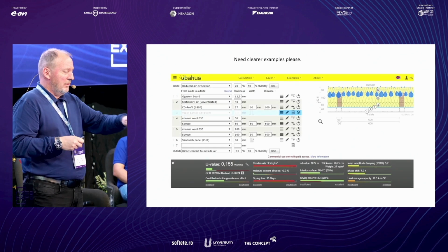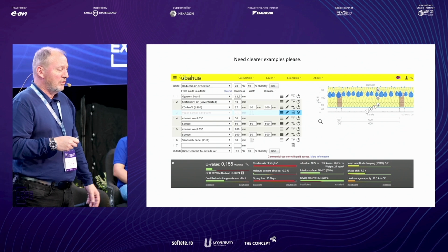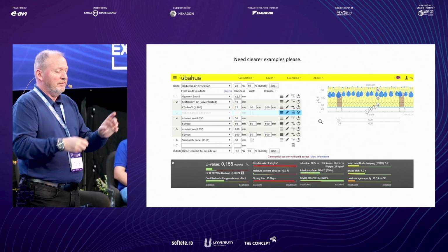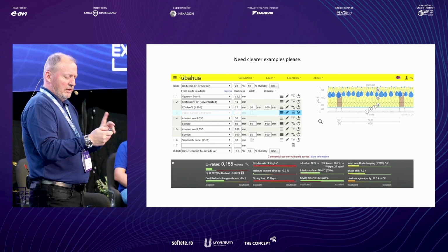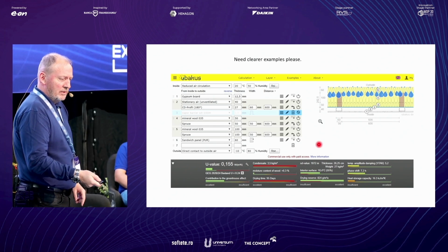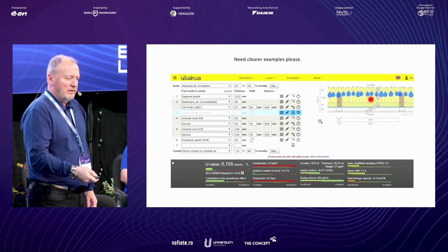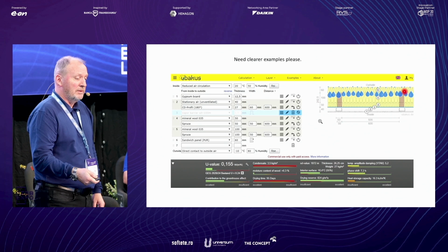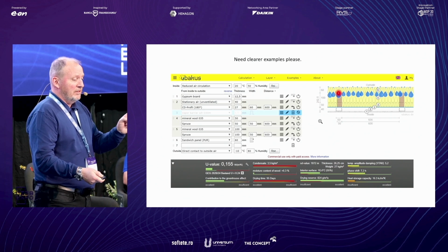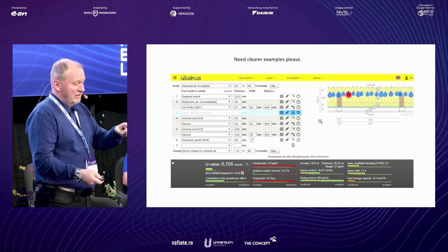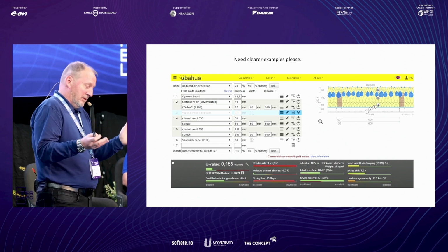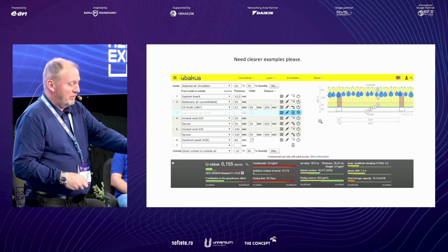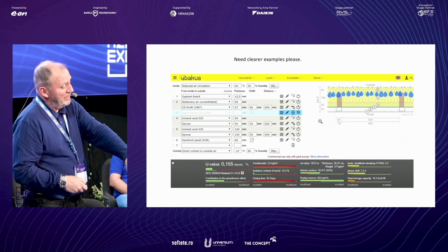This calculation now, we have taken out the air and vapor control layer. I do like this software, really graphical. You can physically see. Now, I'm going to try a button here to see if this actually works. When I say a lovely bit of moisture, as an example, it's great. But in your build, it's not good. And if your insulation gets wet, the thermal conductivity is increased. The building doesn't perform anything like it should, and of course, you introduce a problem of condensation.